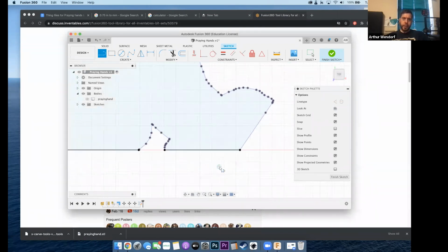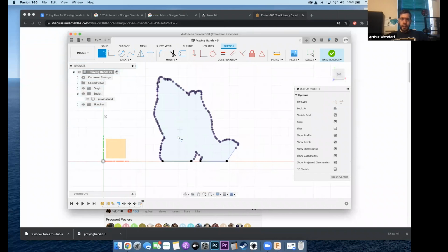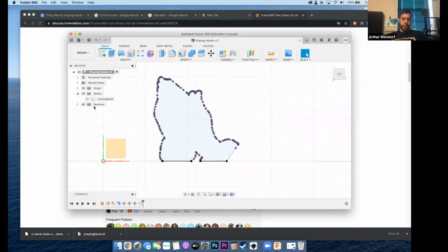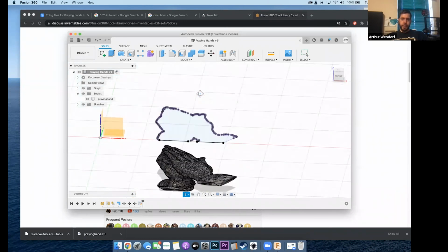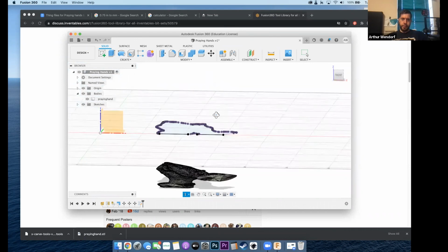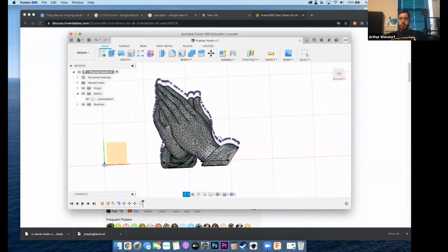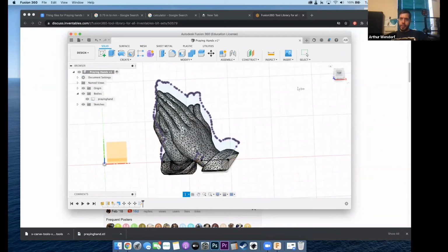Now you'll notice when we did that, this is now working. This has got a nice light blue on the inside and it's different than the color on the outside. That means that this is recognized now as one nice clean shape. Okay, so we're going to finish sketch. We're going to go ahead and turn back on our body so you can see it outlines it nicely. So now we have our body. We have it at the right dimensions, right? It doesn't matter that these aren't on the same plane. That's irrelevant. And we have it in the right orientation, right? With Z up, X to the side, Y going vertical. Okay. So now we're going to save.